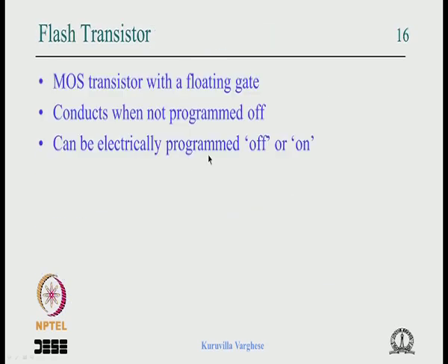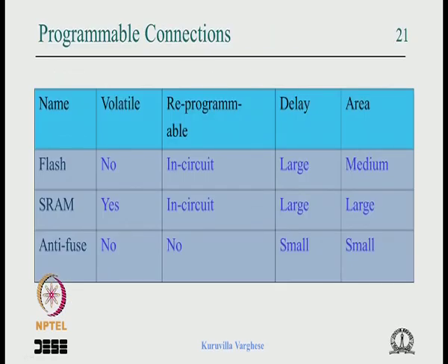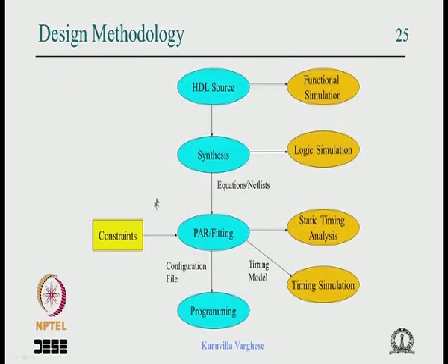So that kind of constraints, called timing constraints, can be specified at this point, which say that for a combinational circuit from an input to a particular output, the delay should be less than a certain time, like 5 nanoseconds for 200 megahertz.